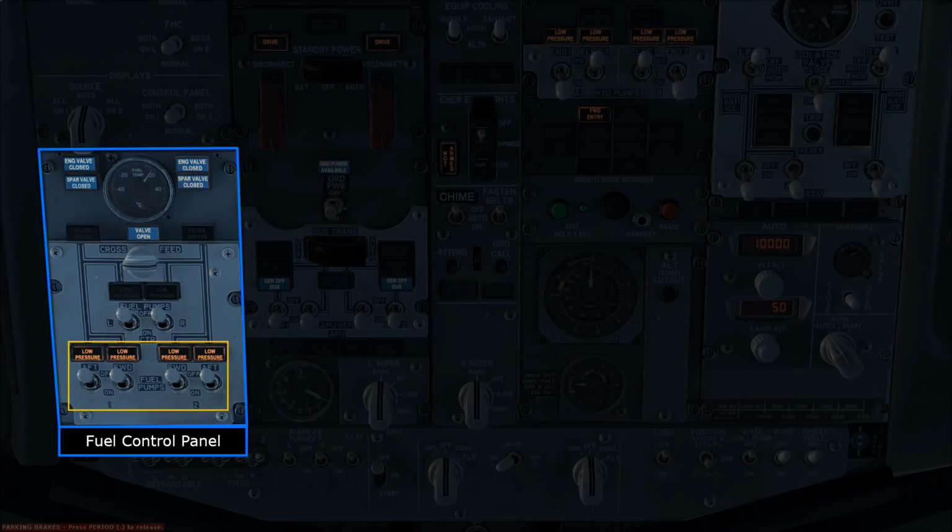Beneath that you have the left and right fuel pumps, again 2 pumps for each tank. So the basic rule when flying this aircraft is that you have all 4 wing pumps working all of the time. If you have fuel in the central tank, you would also switch on the central fuel pumps. The central fuel pumps are actually more powerful than the fuel pumps in the wing tanks, so even when you've got all 6 pumps turned on, the center fuel tank will drain quicker than the wing fuel tanks. Then, once the central tank has drained, you can turn off the center fuel pumps.